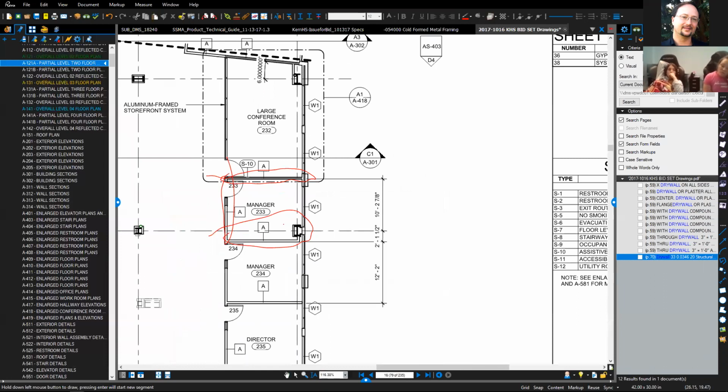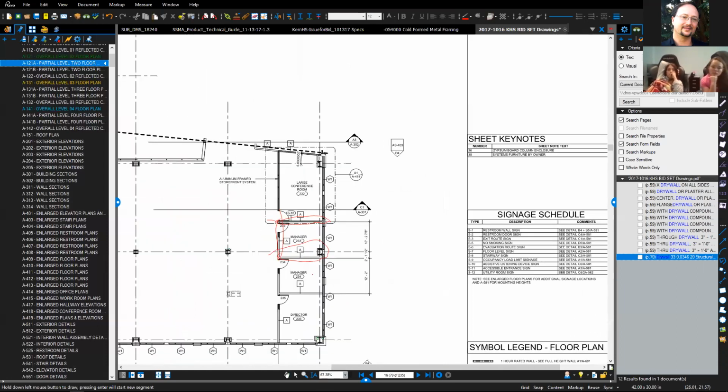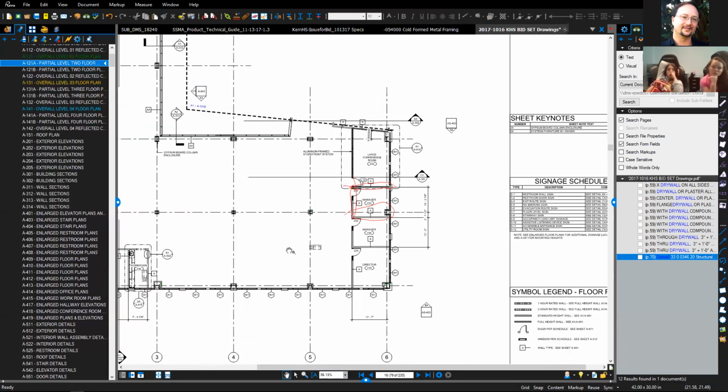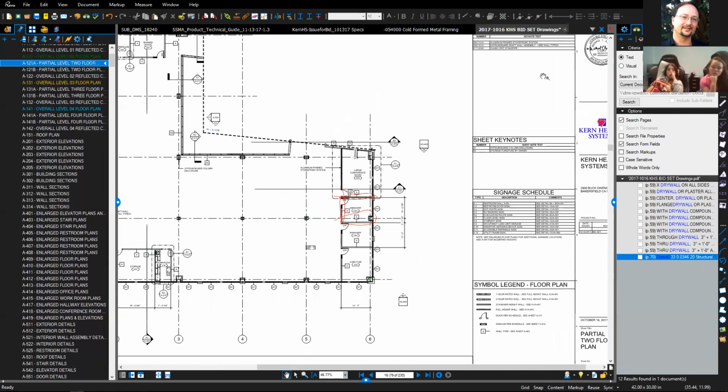When you look at the estimate, it will have all these walls highlighted, which ties into a calculation to build our estimate up. Okay? So we want to be specifying the building material that we're going to be using in wall types 1 or A. And that's where we start to create our submittals from.